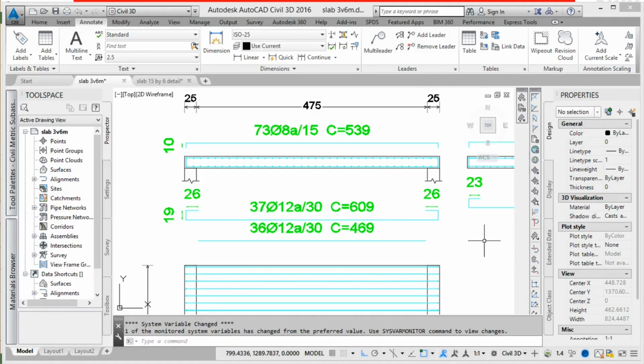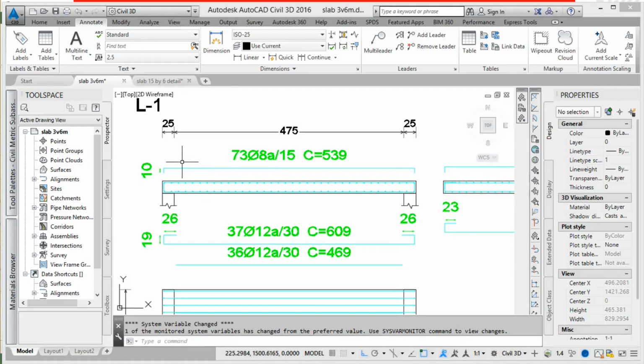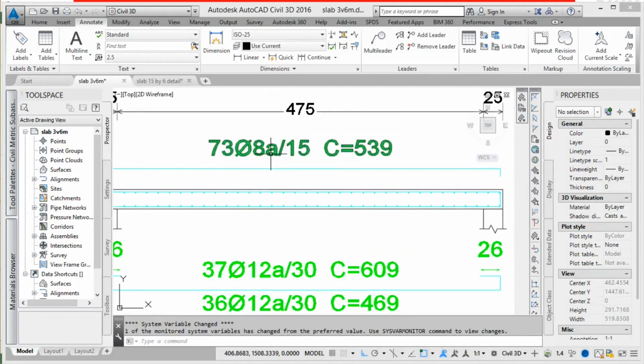This is why this one goes from one side of the support to the other and doesn't go further, because we can put one at this length and another at full length, then we get only the 50% of steel that we need here on the bottom. And on the top, what happened with this connection from one side to the other is what I told you about the combinations. There will always be one combination at some time. We calculate for several combinations, there will be traction here. So placing the minimum reinforcement is good.